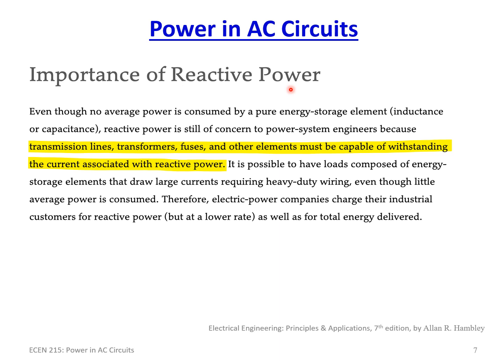Wrong, because there is still current moving to the inductor and then back from the inductor. Granted, the average power is 0. That energy is still flowing back and forth through the circuit, and hence you have to pay attention to that in design. So you always have to know what the actual currents are that are flowing and make sure that your power lines are capable of handling that.